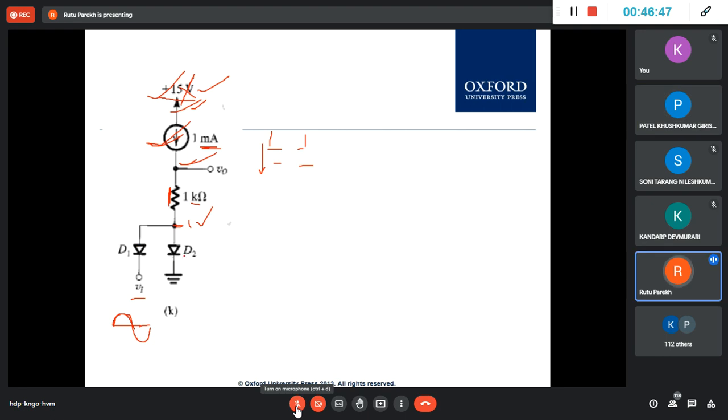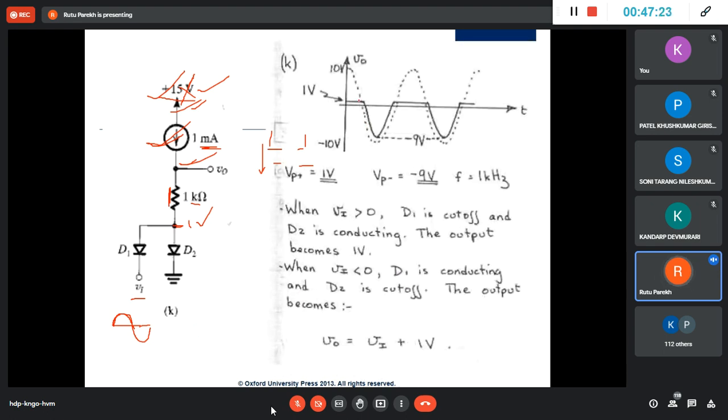Open circuited. So this is open and this is short. It is like this segment is not there, and this is already shorted. This point is the same as this point. So the voltage here is what? 1 volt. Yes, it is 1 volt. So the voltage is 1 volt for this positive half. One minute. See, if I am showing you step by step, then sorry.